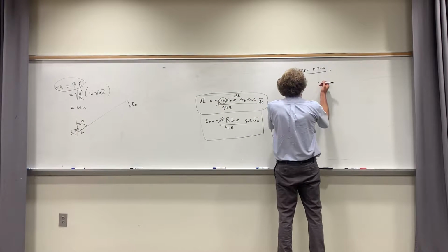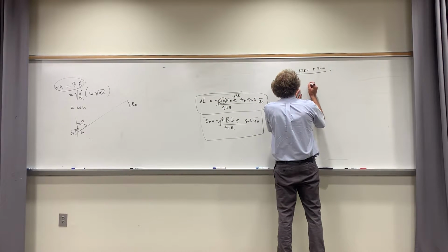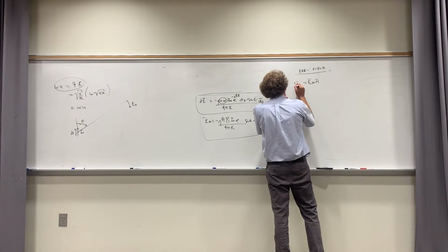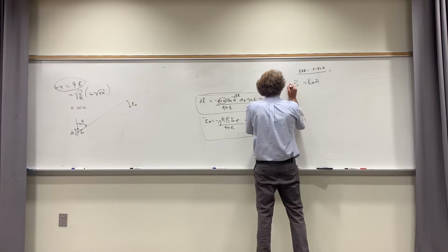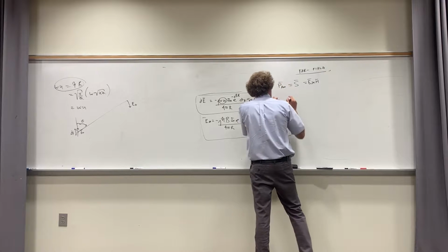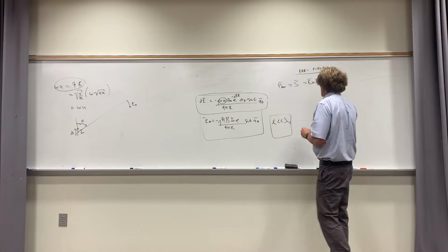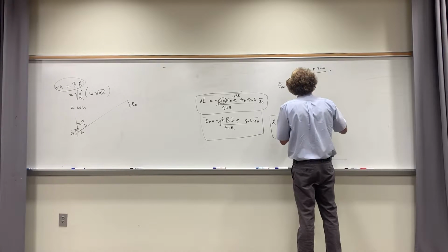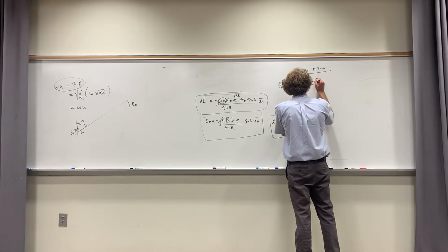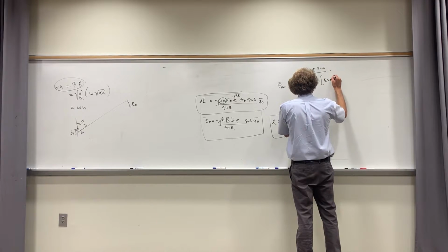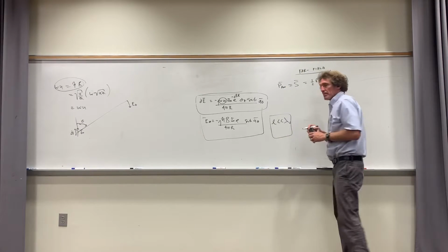If you're in the far field, then I can tell you that E cross H is actually the Poynting vector, what I call S, the power flow. And in Dr. Whitmore's book, he calls it P Av, the power flow, E cross H. And really, I don't want to put the time domain form. It's actually 1/2 times the real part of E cross H conjugated. Do y'all remember that?